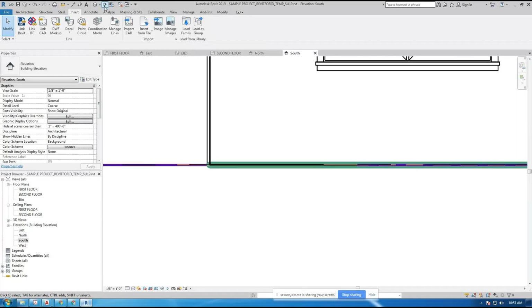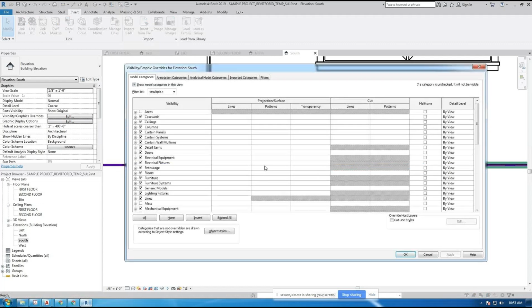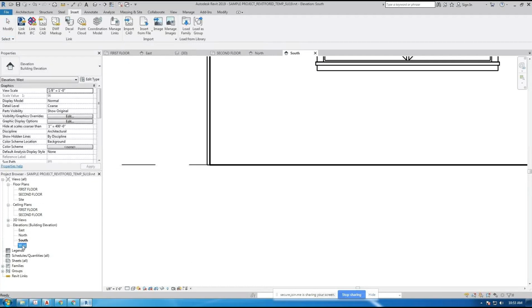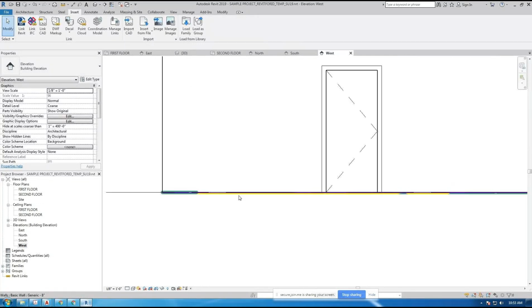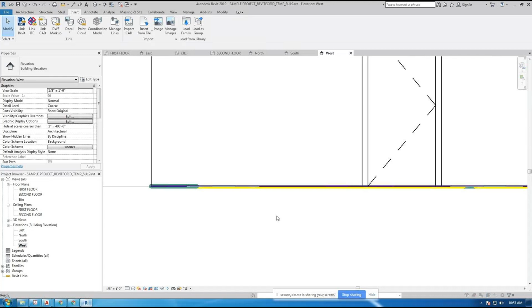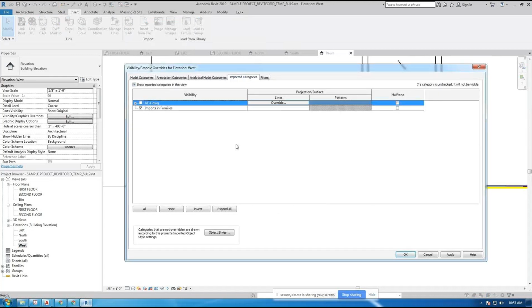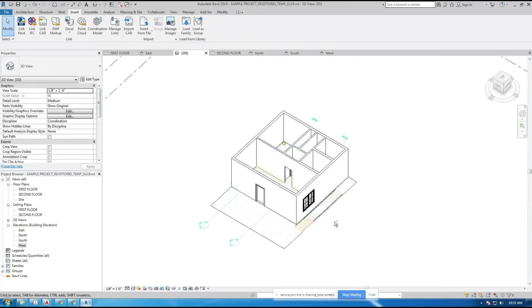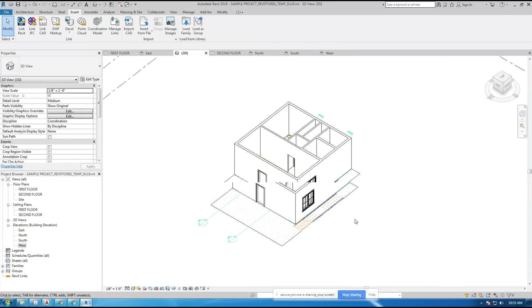This has line weights turned on, right? TL. No line weights, line weights. There's my CAD drawing with its own line weights appearing in my Revit file, which is not good. Which is why I typically type VG and turn off the CAD drawing. And it's gone. West elevation, same problem exists. VG, turn off the CAD drawing. Because typically I like to see my floor plans in my 3D views. That's the only reason why I'm proposing we keep the CAD drawing in all the views.